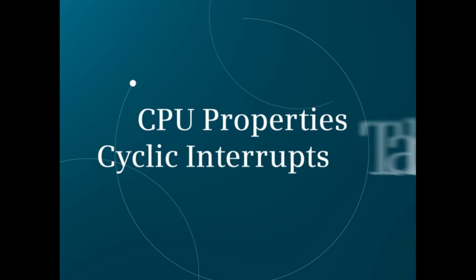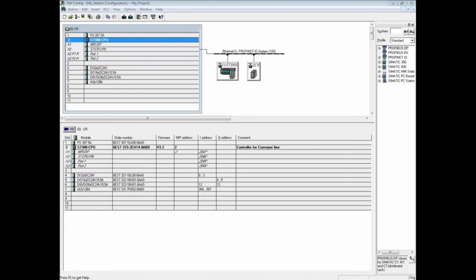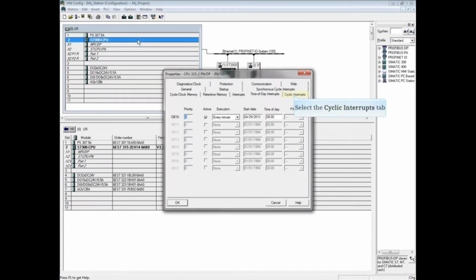This video shows the CPU Property Cyclic Interrupts tab in the hardware configuration. With the hardware configuration open, double-click the CPU to open its properties. Click the Cyclic Interrupts tab.